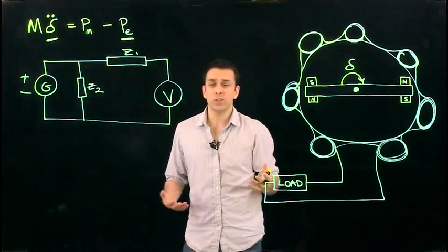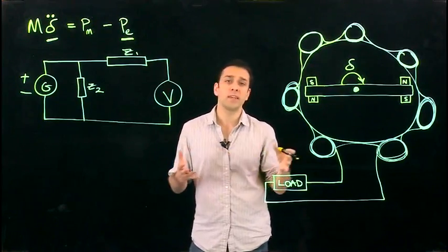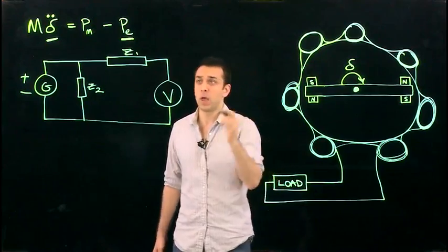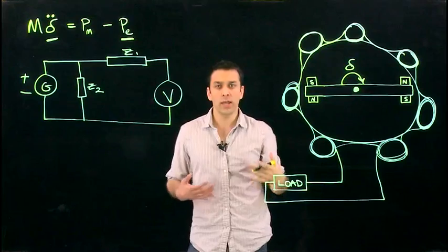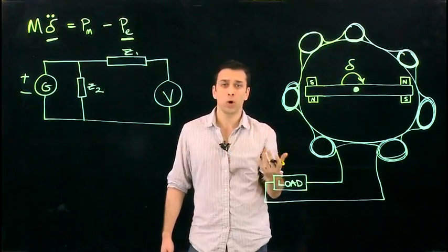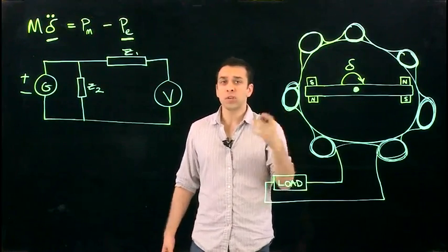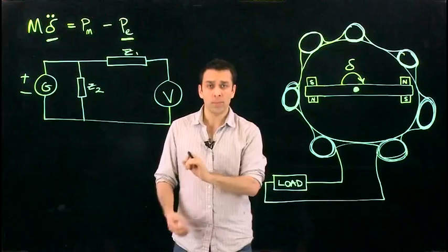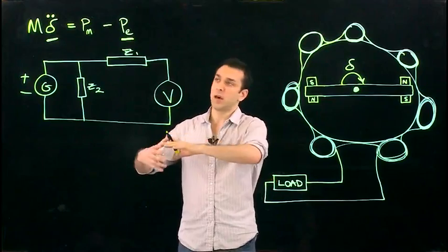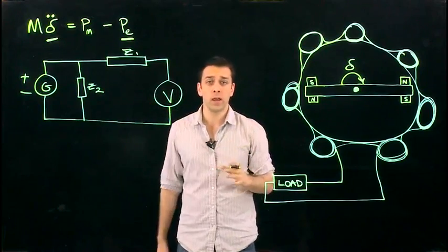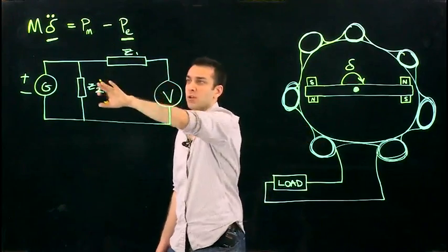An impedance, in AC terms, is basically just something that resists the flow of AC current. It's like a resistor in a DC circuit. So basically, current flows out, and it's flowing through all these transmission lines, distribution equipment, the transformer I was talking about earlier. We're modeling these as resisting the flow of AC current. So just like a wire in a DC diagram can heat up as current flows through it, and it'll resist current flow, same thing kind of happens with all this distribution and transmission equipment in the AC world. And so we have the AC version of resistance, impedances, shown over here.